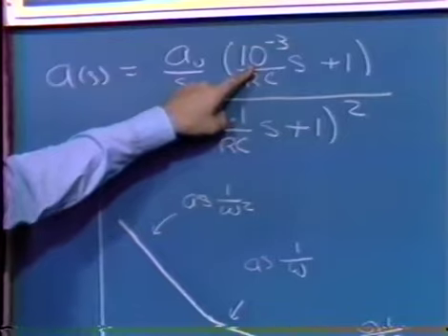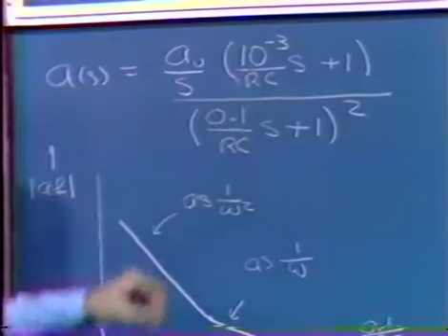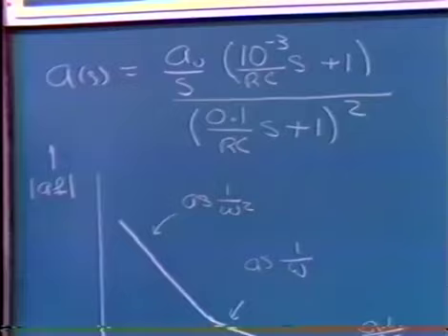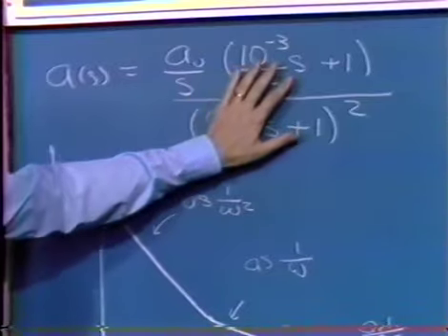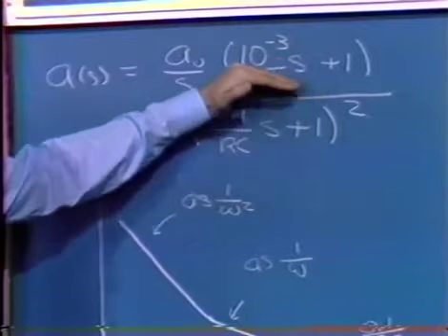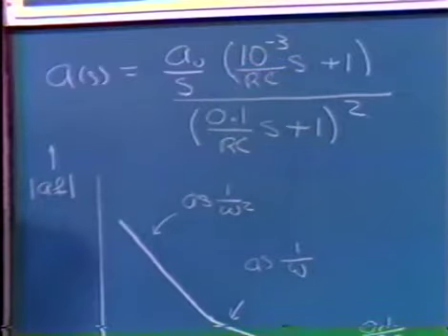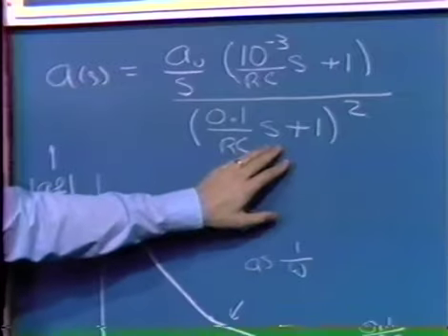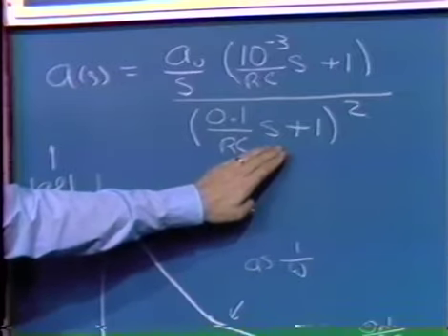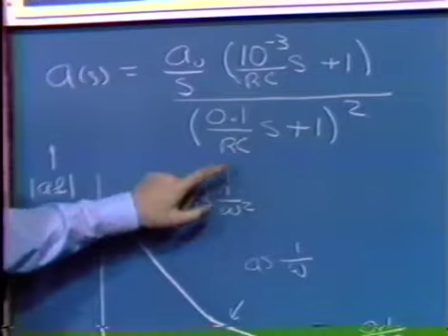Let's put the 0 a decade below that. That's quite conservative. We said with lag networks that we might start there, but then edge up. Let's put a 0 so we have a 1 over S slope that starts a decade below nominal crossover. And then I'll put 2 more poles that provide filtering a decade above nominal crossover.